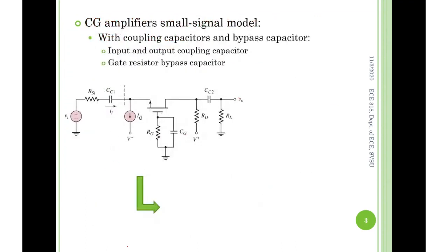In the last lecture, we did two types of circuit, common source and common drain, right? Today we are taking care of the third one. It's common gate. Look at this given circuit. The input is VI, the AC input. Where is it going into? Going into the source, right? So the input is the source. The output here is the drain, right? And that's why this is a common gate.